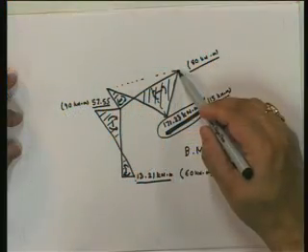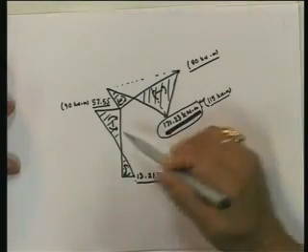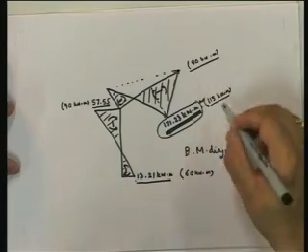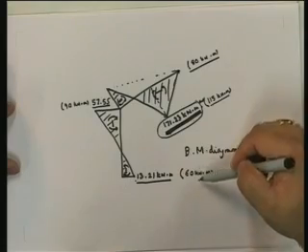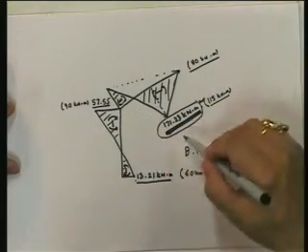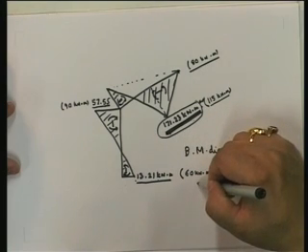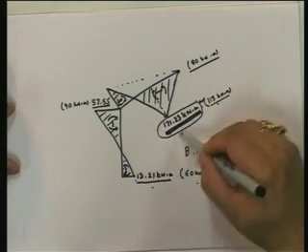Okay? So now if you look at this, would you say that increasing the flexibility of the structure makes it better? No. In fact, by restraining the rotation here and making the structure stiffer, you may have increased the moments. However, you've made the moments much more even. You see the difference between this and this, and this and this. The lowest moment here is 60 kilonewton meter, and the highest 115. Here, lowest 13.21, highest 171.